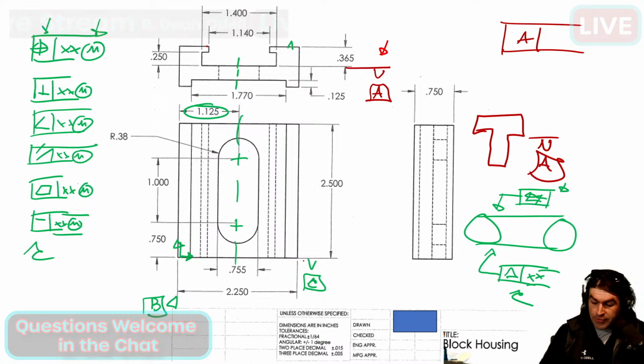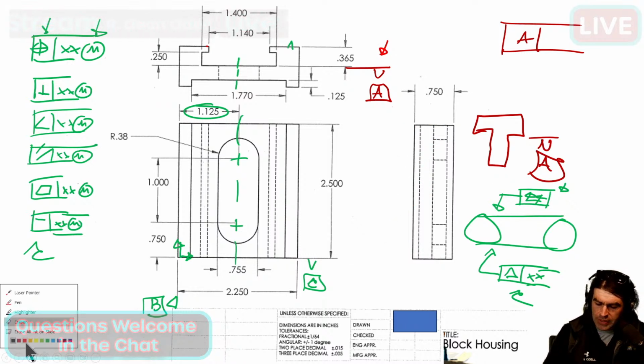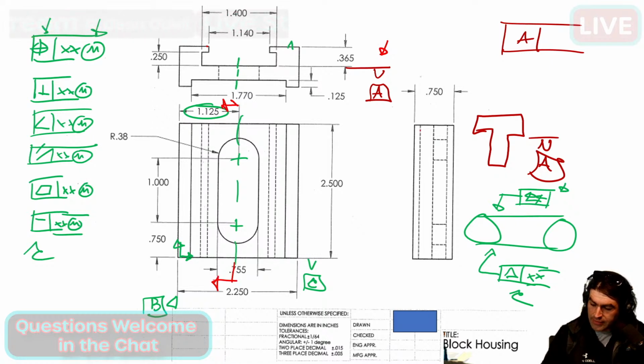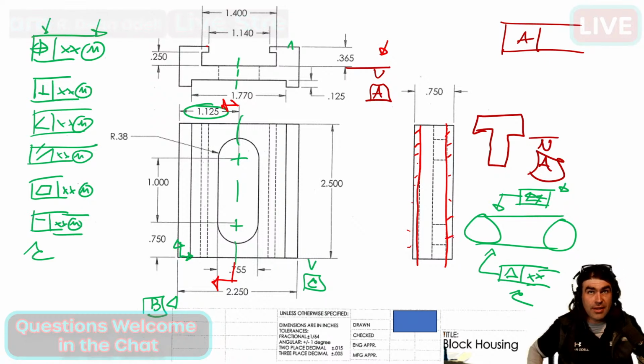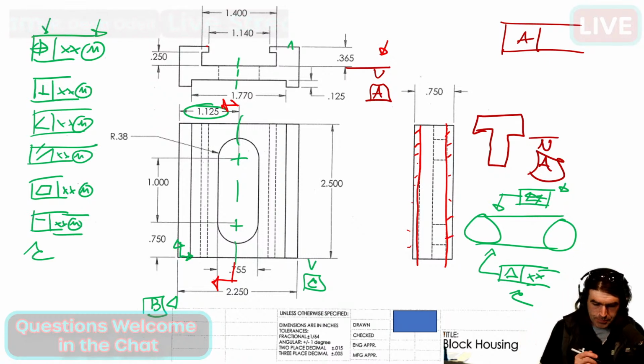So we've got our datum reference frame here. Again, with these tangent lines, woof, it's just ants marching all over the place. I would totally get rid of all of that. Or if you really needed it, you could section this. So I just put in some lines. If I section it, now they can all become nice visible lines with section lines. That's the way I would have gone here.